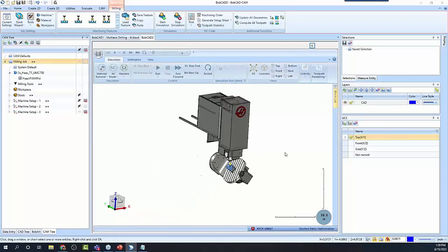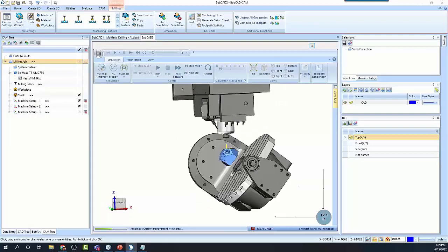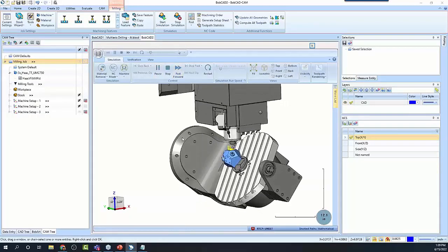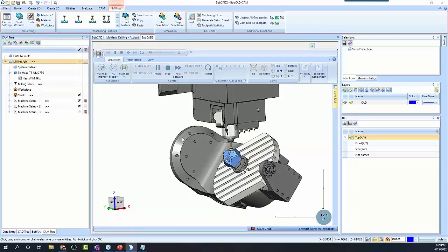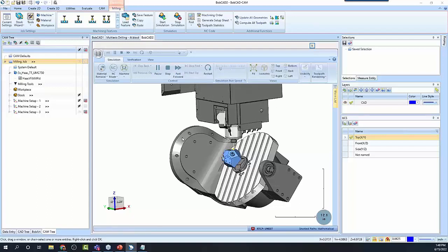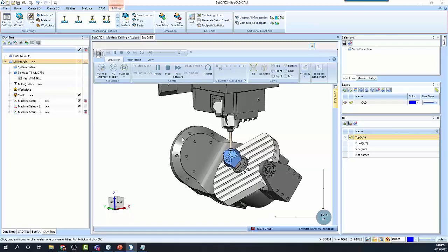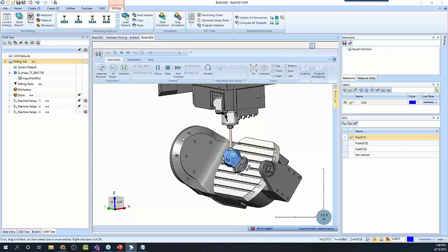This one again, instead of shifting in X and Y, we use Z, and you can see how the part is off the table there. With the index systems, you can see the difference between the linking. The other one was interpolated, and this one was clearance and then direct move. So a little different motion on the machine. Something you have to pay attention to for your clearances, right? But again, we've gone through and drilled all our holes here.